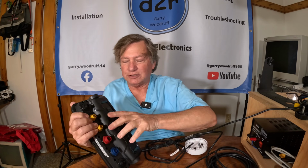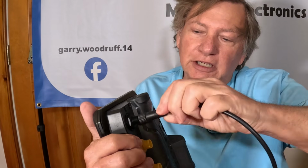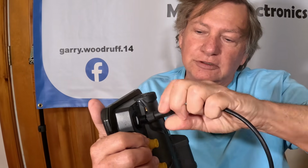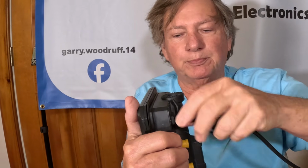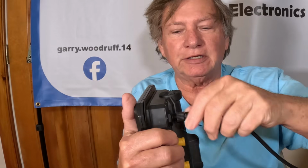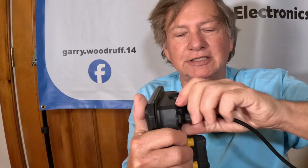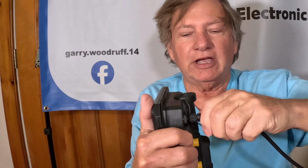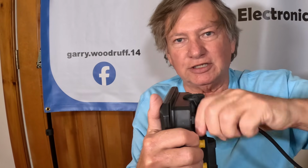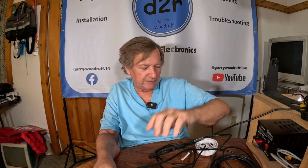The easiest way I found to connect those in is once you get it lined up here, as you start putting it in, I twist it a little bit and push the pins in a little bit. What that does is it makes it a lot easier to go into the connector, and that way you're sure that as it goes in, all the pins are fitting. So this unit is now connected to the NMEA bus.